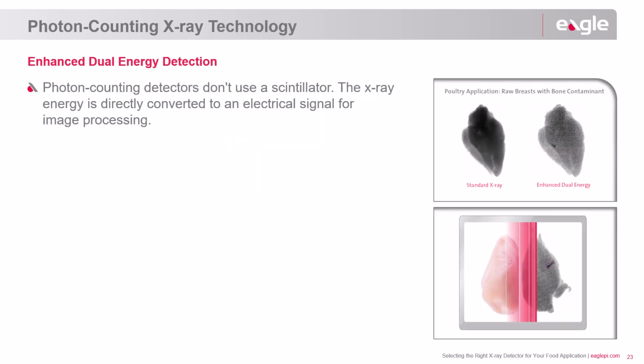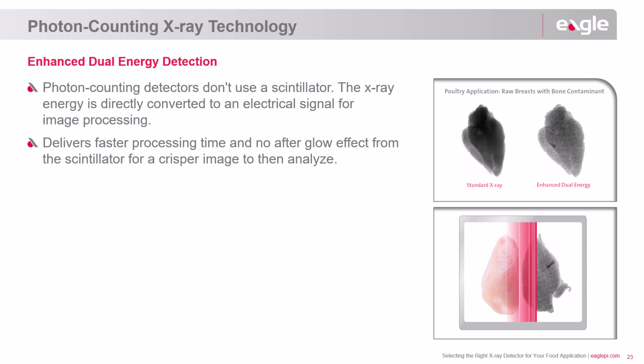The latest advancement in imaging technology is photon counting, which represents a significant departure from traditional systems. Unlike older setups that rely on scintillators and photodiodes, photon counting technology converts X-rays directly into electrical signals. This direct conversion leads to faster processing speeds and eliminates issues related to afterglow in images. In conventional systems, scintillator materials emit light when exposed to X-rays, and this light diminishes slowly after the X-ray source is removed. This lingering glow can cause blurring in the resulting images.